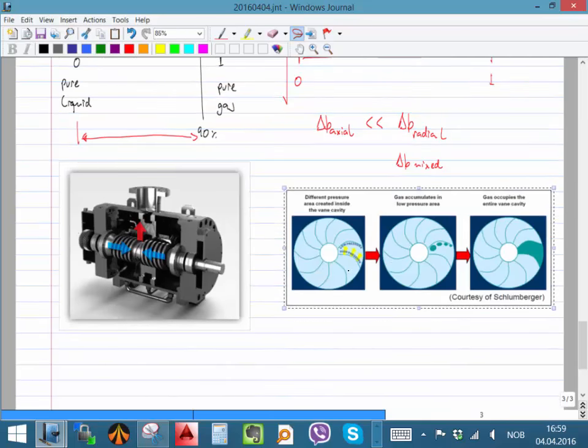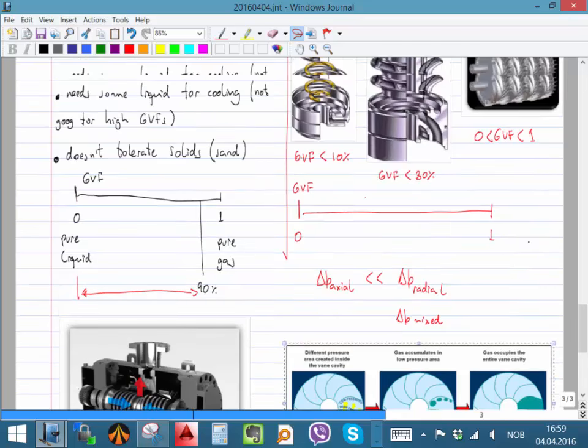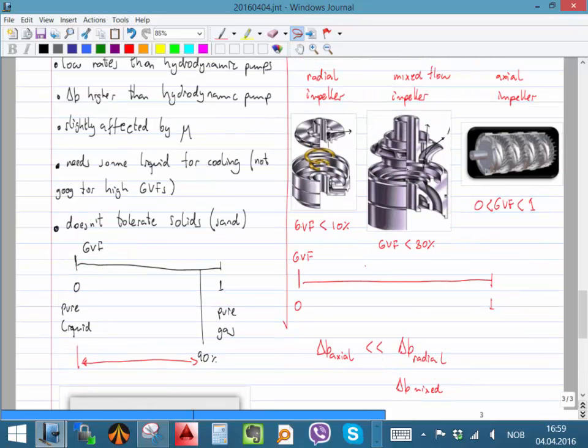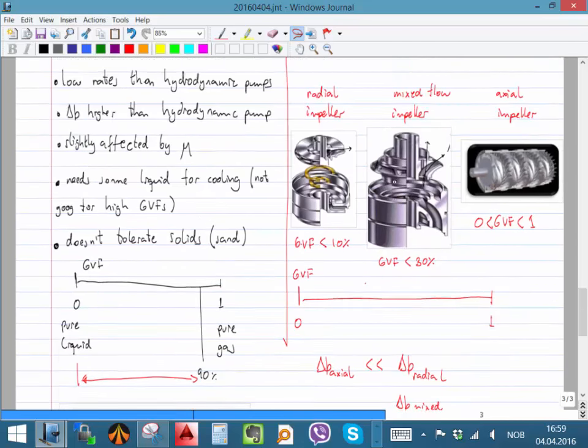And you recognize this view, right? It's from the front. Okay, the fluid enters here and then it goes to the side. Okay, it's kind of a front view. If we remove the cover of the impeller, then we will be able to see that. And actually, there is a separation of the gas from the liquid that happens in the axial machines or in mixed flow machines, but it's not so pronounced. Okay, it's not such a strong separator.